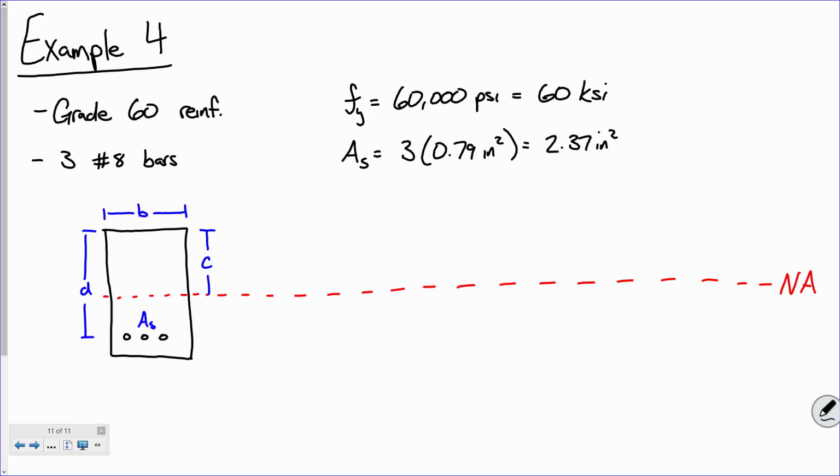Now, theoretically, if I were to define a bending stress profile, it would look something like this. It'd be nonlinear, something like that. And this would all be compressive stress. Then I would have some contribution down here from tensile stress. That's my theoretical stress distribution. Right now, I don't care about that. I've got to be able to use something, so I'm going to draw the real stress distribution here on the right.